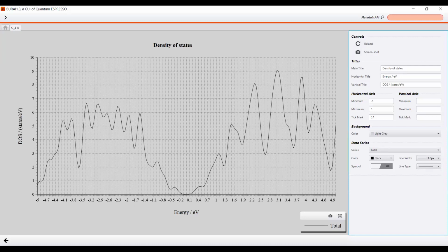You can also, if you want the XY data and to plot the density of state differently, go to the folder which is SI4 and find the PDOS values for different orbitals, which is 1s or 2p for silicon or any other metal. And if you want to analyze the charge, you can also analyze the charge transfer or value of charge from these files. Okay, so this is the partial density of state for different orbitals, and you can plot it using different plotting software. So all the things you can find from the folder if you want to analyze further.